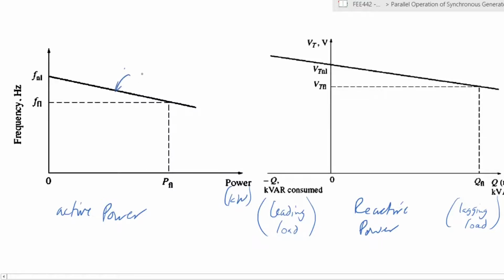And you can see that you have a slope SP that determines the characteristics of the reaction of the generator to any change in the load. The droop of speed. When the generator is supplying a certain power FL, let's say the full load power, it will be at a frequency that is given by that. As you decrease the amount of power the generator is supplying, the frequency will naturally increase, because of the characteristics of the governor. So the governor keeps that relationship in a linear form.